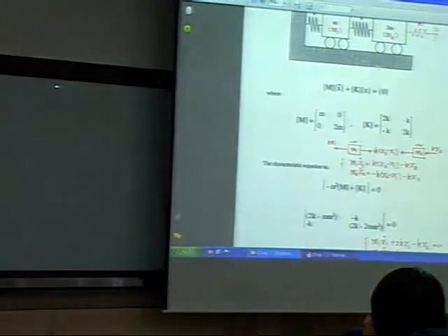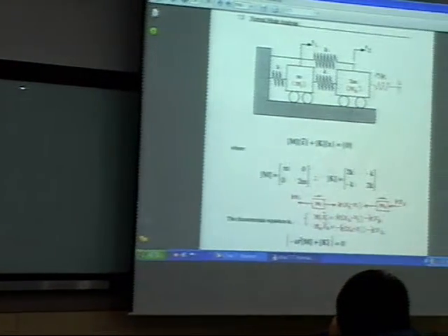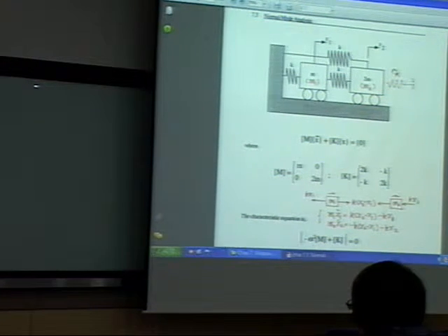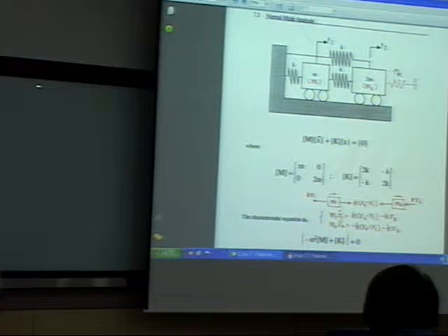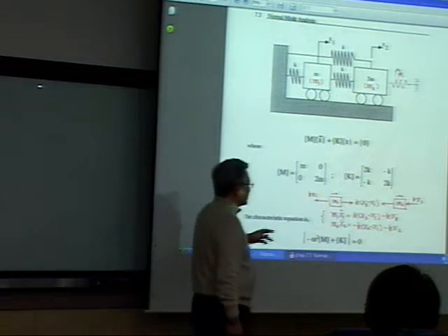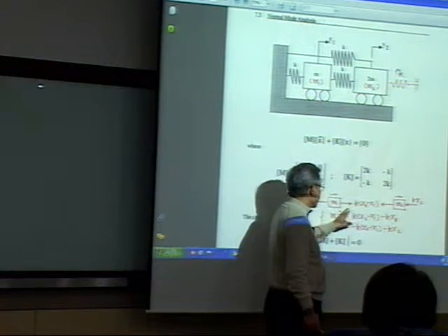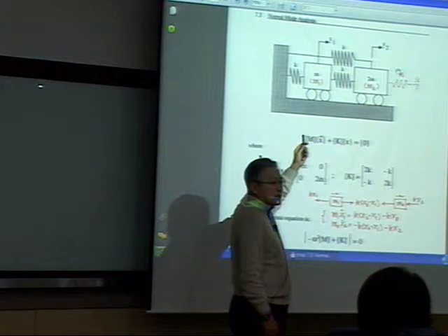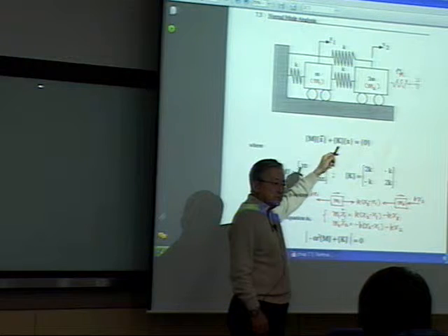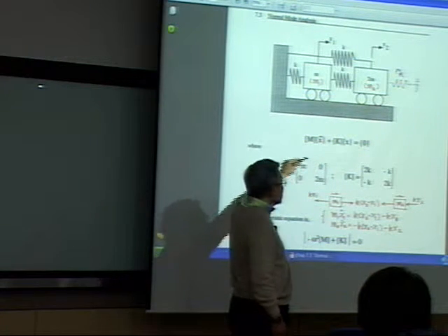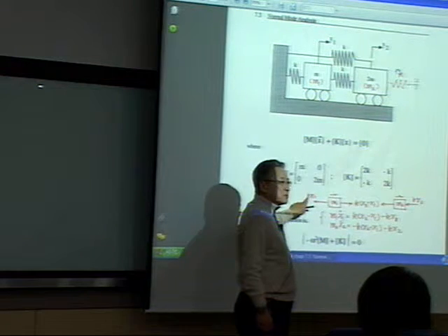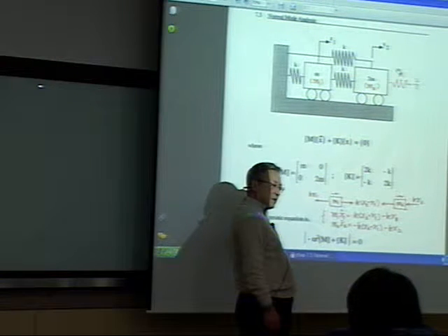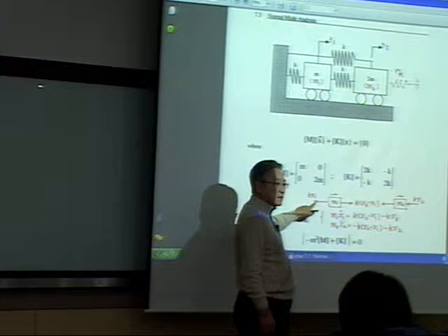So this is better. Newton's second law is what I said you should use. Let's look at the free body diagram around M. If you just press x1 in the positive direction, which is the direction to the right, okay? If you press it in that direction, this is simply kx1. If you cut the spring, you have to hold in that direction. So this is kx1, okay?